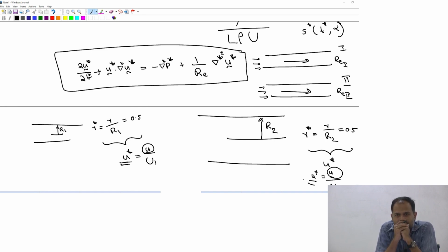Yes. No, oh, okay, sorry. So I'm talking about here the Reynolds number being different, and therefore Reynolds number is the parameter. If you want to get this match, the Reynolds number in problem 1 should be the same as the Reynolds number in problem 2. Then only you get this match. And that's the beauty of talking about it. We don't care about what are the actual dimensions or the fluids. In fact, this is a very important principle that is used when you have to make models in a lab instead of testing out in a field, which we'll discuss next week. And this is a principle that we would use.